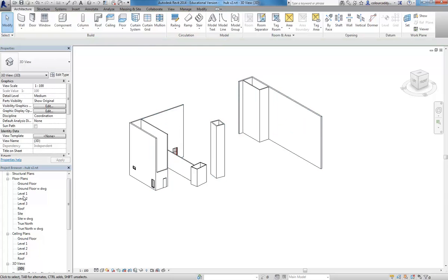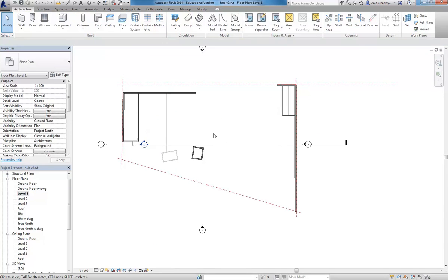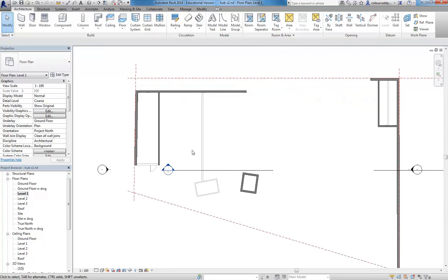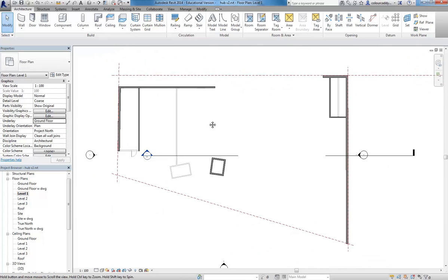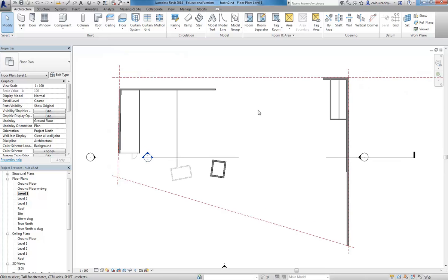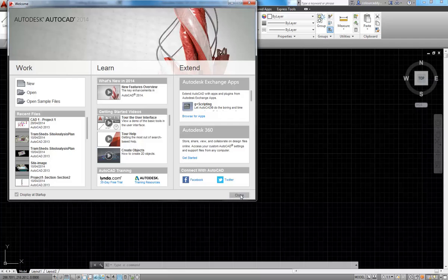So that's it, and then you can go to the next level, and you'll see then that it should start making sense because the walls on only the ground floor will come in greyed out. If they don't, or if you want to change it to show something else, that's because of the underlay setting here. So the underlay is the level below ground floor. You can adjust that. And so now I could draw, again, the walls that would only be on this level. And there'd be a lot. So I've got a floor plan for that.